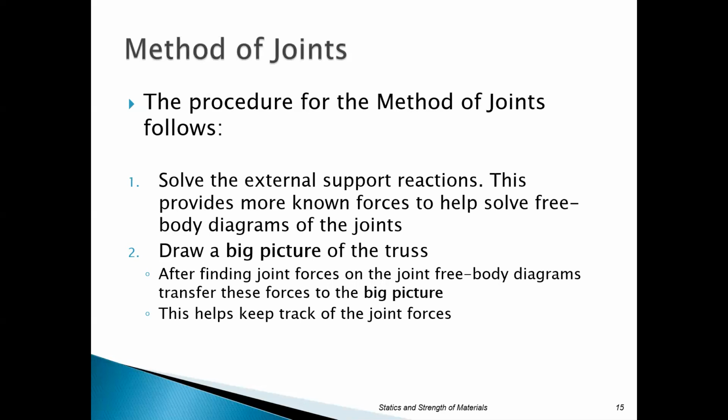Okay, so you're going to have to learn how to do this at some point, because when you get into all these problems, if you blow your reactions, you've blown the truss completely, and you will never get it to resolve to 0. Right? So we're going to have to solve support reactions first.